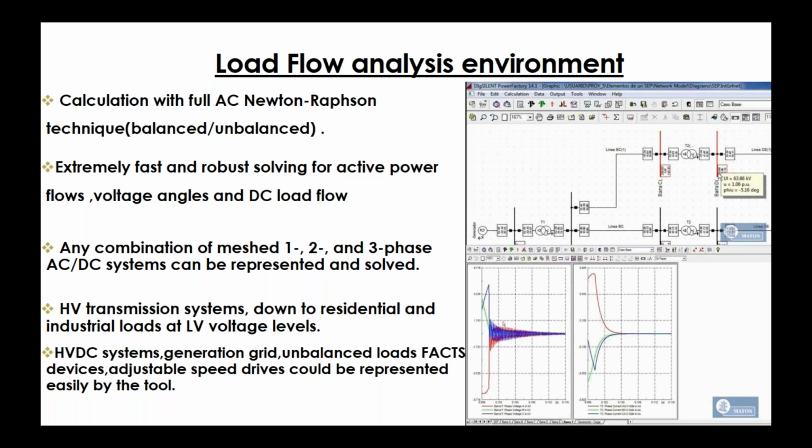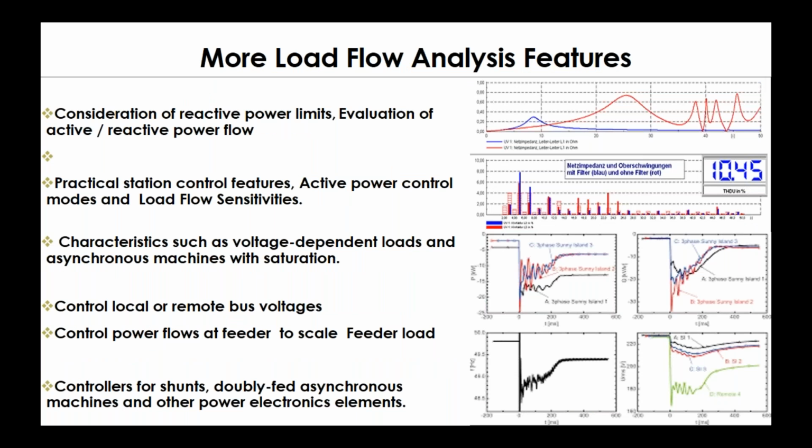Neutral conductors can be modeled explicitly, and the load flow tools accurately represent unbalanced loads, generation, grids, and variable neutral potentials, HVDC systems, DC loads, adjustable speed drives, and FACTS devices for all AC and DC voltage levels.